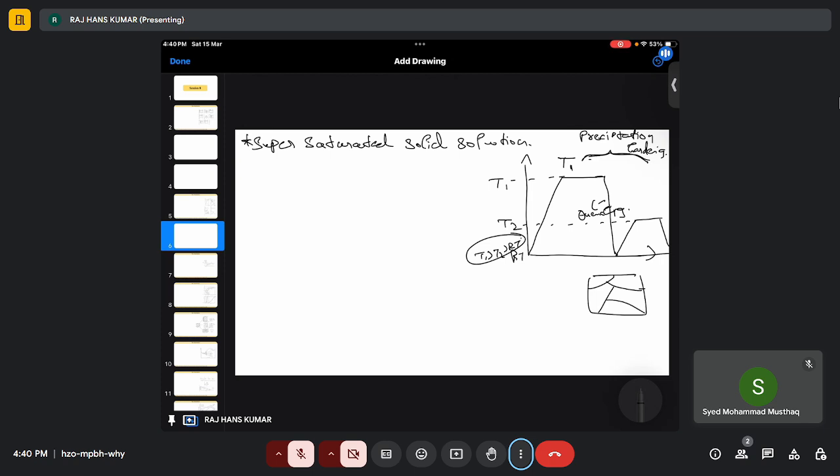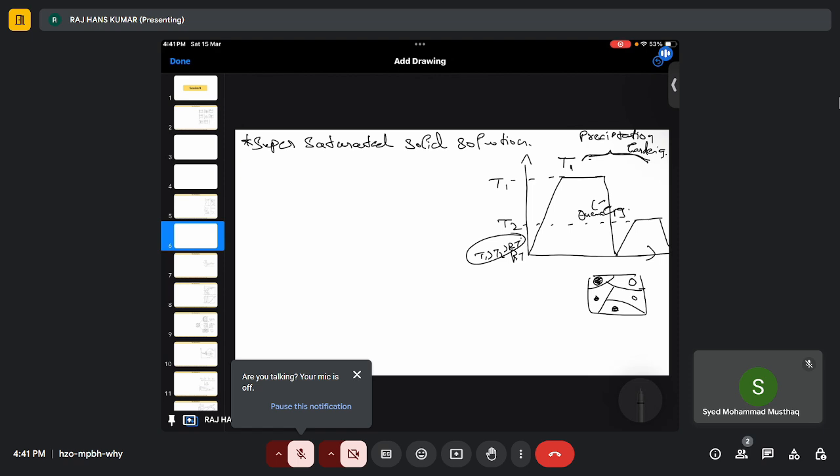Because of the saturation, after heating, you will find precipitates. So in the alpha phase, you will find a different type of phase, the beta phase. You can control the size of it by doing this type of process. So this is called a precipitation reaction, or precipitation formation.